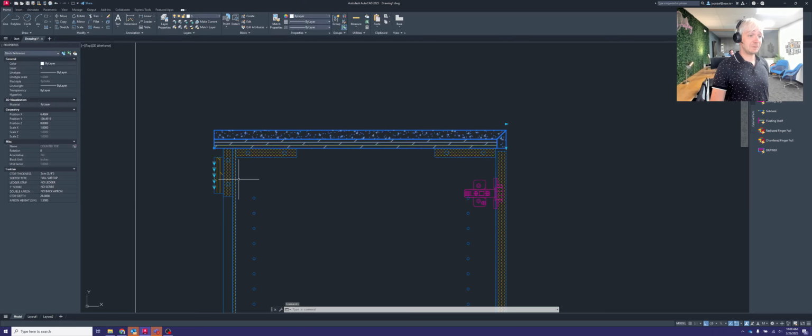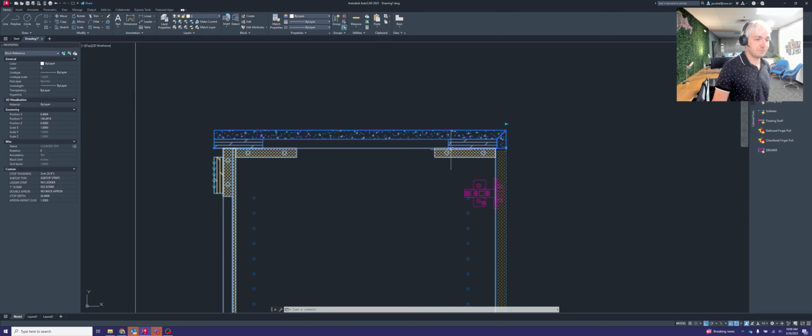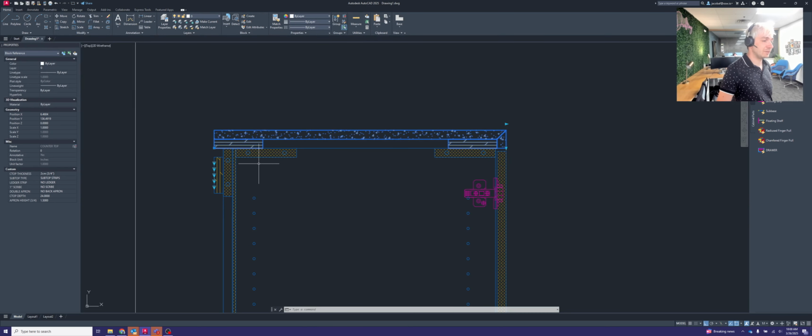A full subtop is going to span the front to the back of that counter. The subtop strips are going to be just the front and the back only, at 4 inches wide. Or maybe actually, I think it's 5 inches wide, but they're just strips of material that sit right there at the front and the back. That's to help save on material costs, but also make sure that we're still supporting that countertop as necessary.